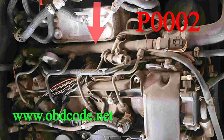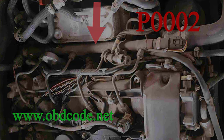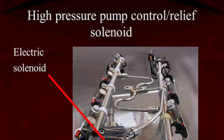Here are some additional tips for diagnosing and repairing code P0002. Check the wiring and connectors to the fuel volume regulator for any damage or corrosion. Test the fuel volume regulator to see if it is functioning properly. If the fuel volume regulator is faulty, replace it with a new one. If the wiring or connectors are damaged, repair or replace them. If the PCM is faulty, it will need to be replaced.